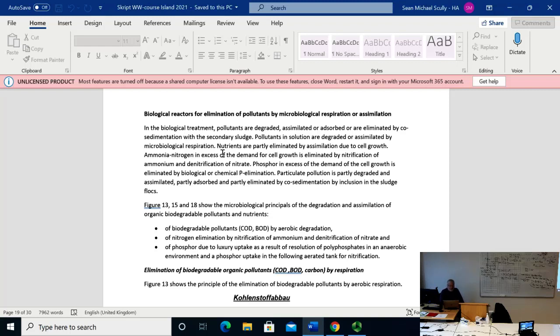But this is only the organic part of it. 70% of the bacterial mass is organic, 30% is mineral mass. So the whole bacterial mass you will have is going to be 44.6 grams. You take 100 grams of COD.